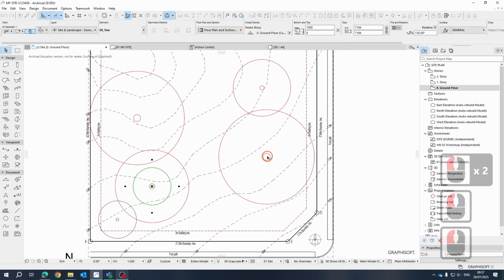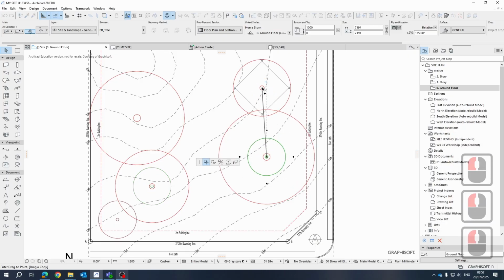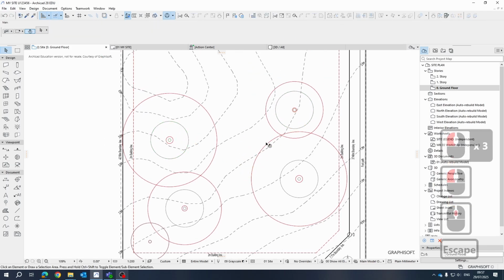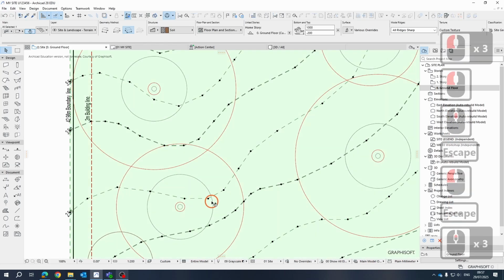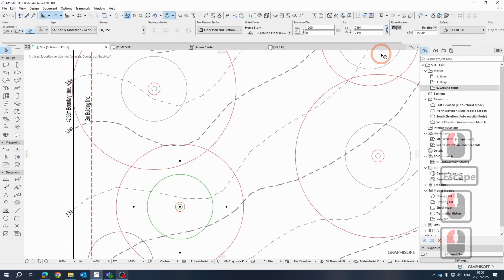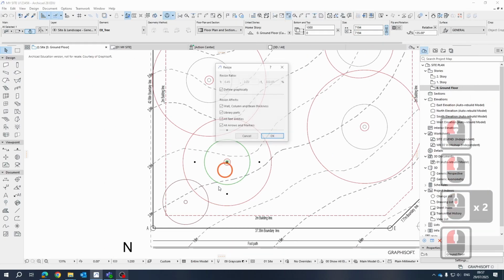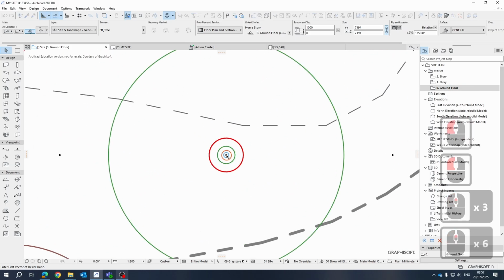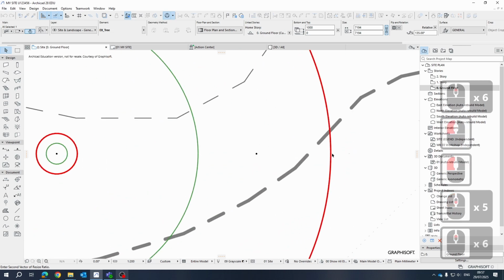Control, drag. So this is a quick way to do it. Control, Control. So just quickly add your trees. Then when you're done, get them to the correct scale. If you're going to scale your trees, just remember you need to lock this dimension, and then I just simply use the scale tool, press OK, because it allows me to say, well, I want to scale you from here, and I want it to scale to this line over here.